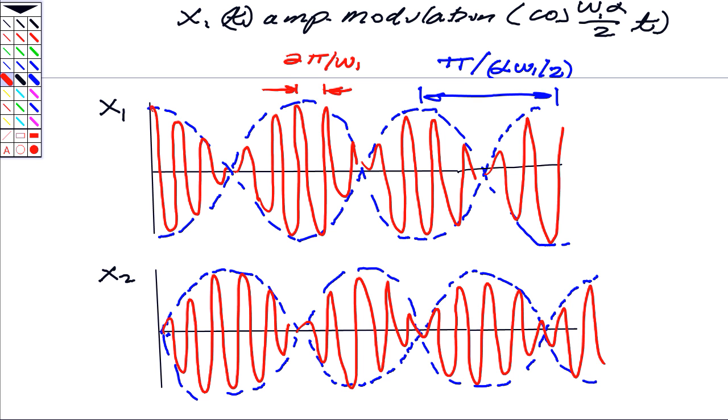Anyway, the point of this example is that when you have systems with frequencies that are close together, if they are modally coupled, then you should fully expect this kind of response, because it's in any system where you add together two harmonics like cosine or two harmonics like sine, where the frequencies are very closely spaced.